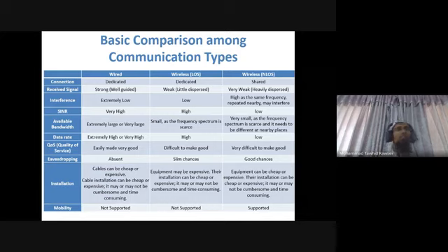Now the bandwidth for LOS communication. Since you are confined, a large share of many people will be able to use the same frequencies because you are confining your radiated power. So you're not interfering. If you use large bandwidth, it is not disturbing others. In the case of wired, you can even see in optical fiber, it is in the order of terahertz. Very large bandwidth you can use. You have dedicated communication. The wire has some maximum capability that will restrict the upper limit of your frequency. So you have wide bandwidth.